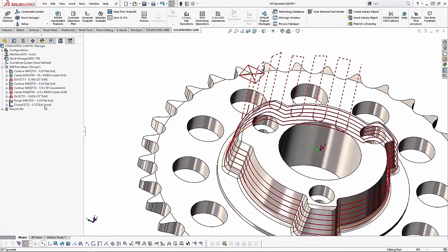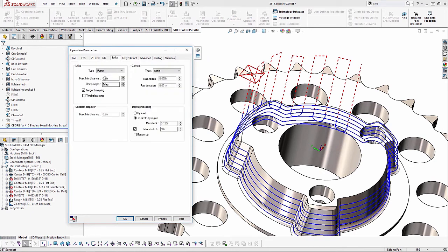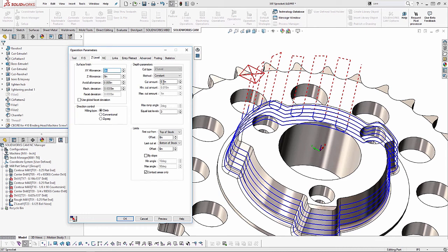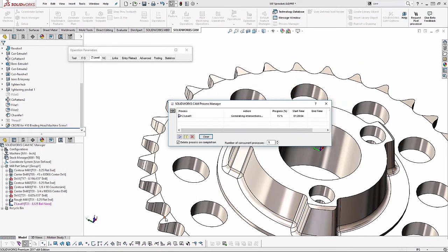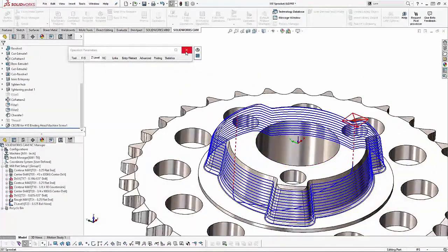All right? A couple more things we might want to do. There's some unnecessary lifting there, so we're going to go ahead and make some adjustments. We will tell it to cut a little bit finer. We'll say 50 thousandths cuts. Something like that.